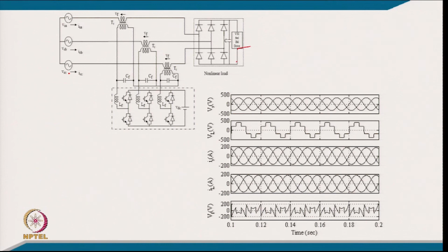So, virtually we are using a series active filter for a voltage fed kind of load, reducing the current harmonics, which could otherwise have been very high. The THD of the current otherwise, if we do not use it, is around 60 to 70%, and we are able to reduce it to even less than 5%. So, after making the complete model with realistic data, we are able to get the result here.